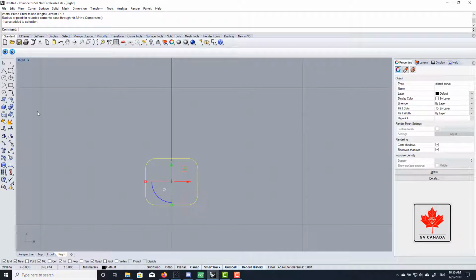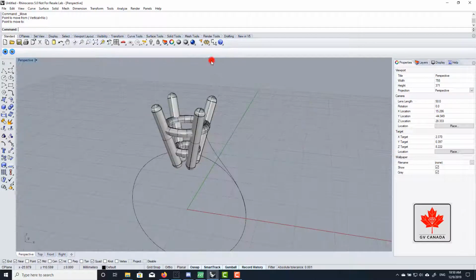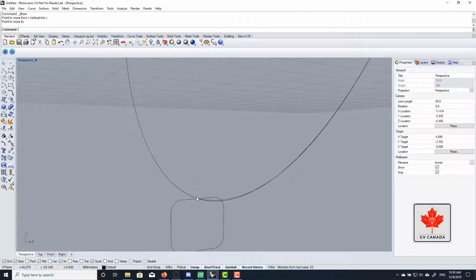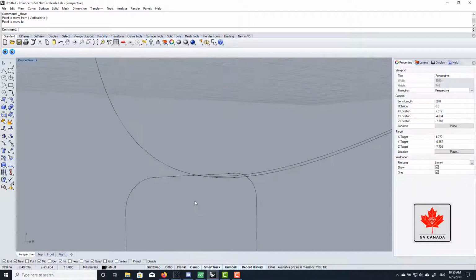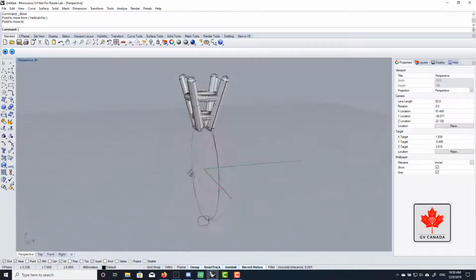Click on that, and we're going to move from the top here, so mid of this line here, down to the quad. So just to confirm everything worked, we'll go to perspective view, rotate this a little, so as long as the bottom of my profile is touching, or you can say in this view top, is touching the center or quad of the ring round.